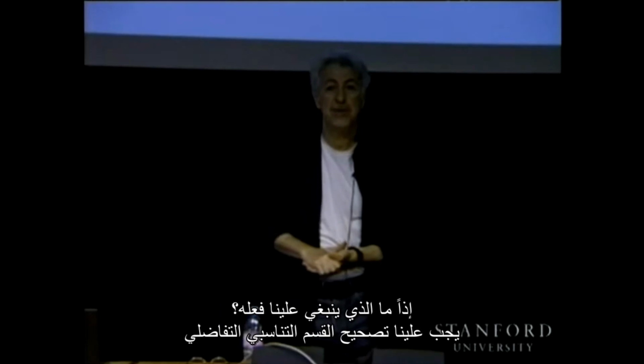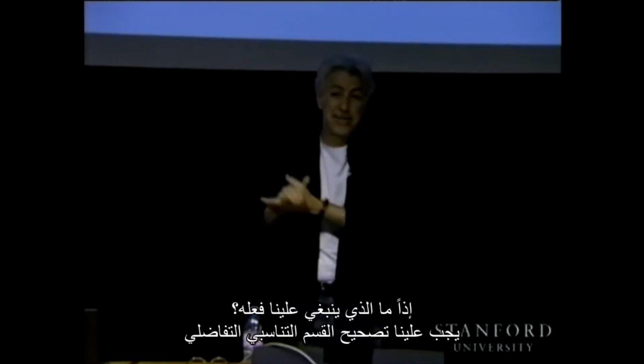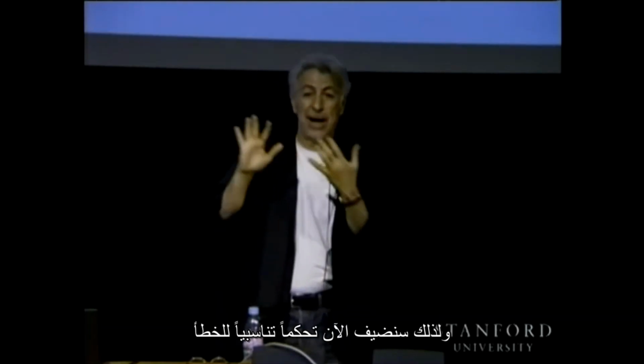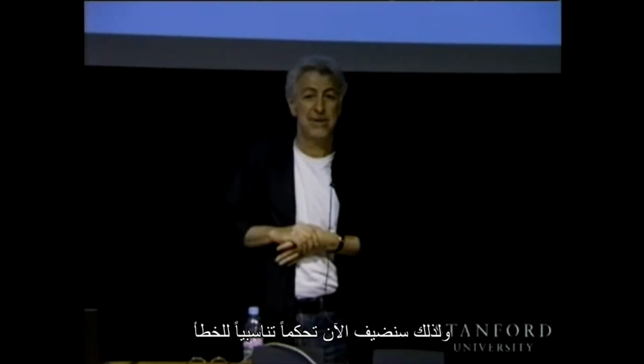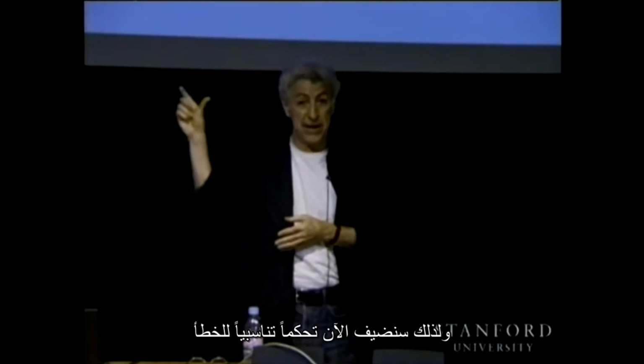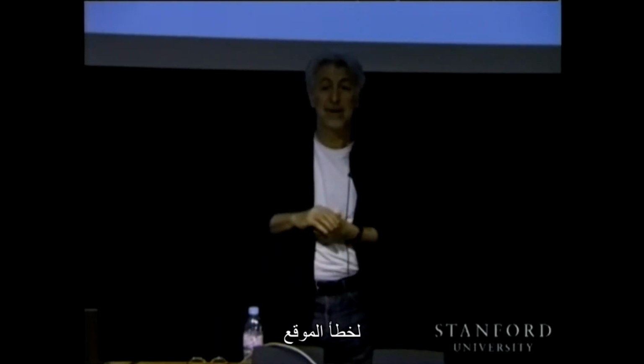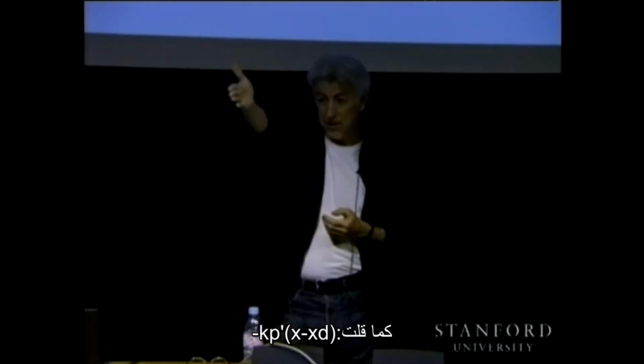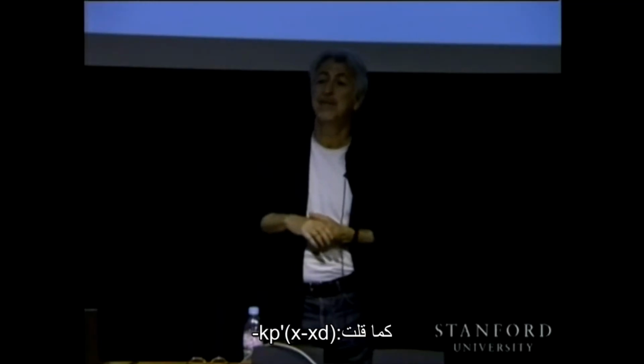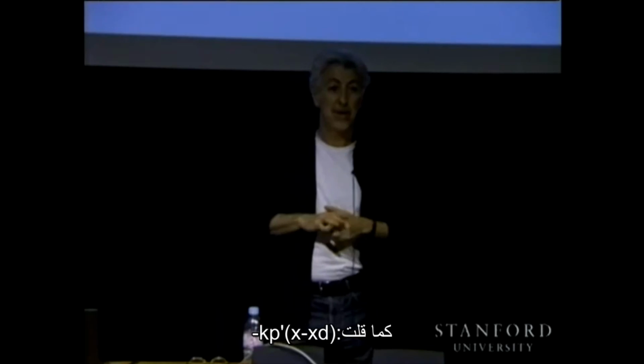So what should we do? We should do the PD part. And that's why now we are going to add proportional control to the error, the position error: minus kp prime, x minus x desired. What about the error in velocity?